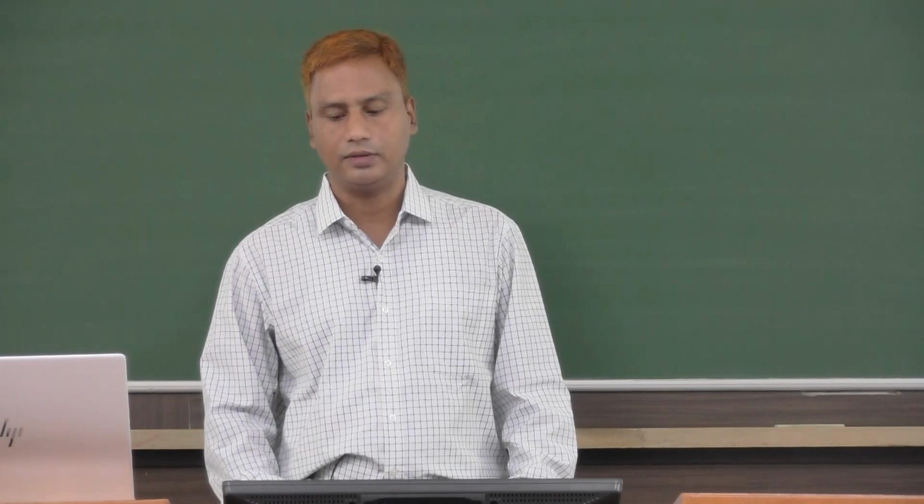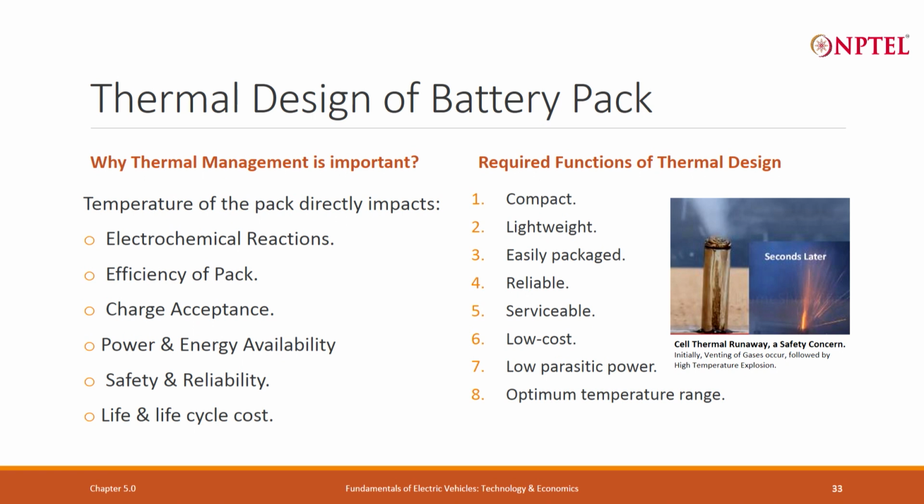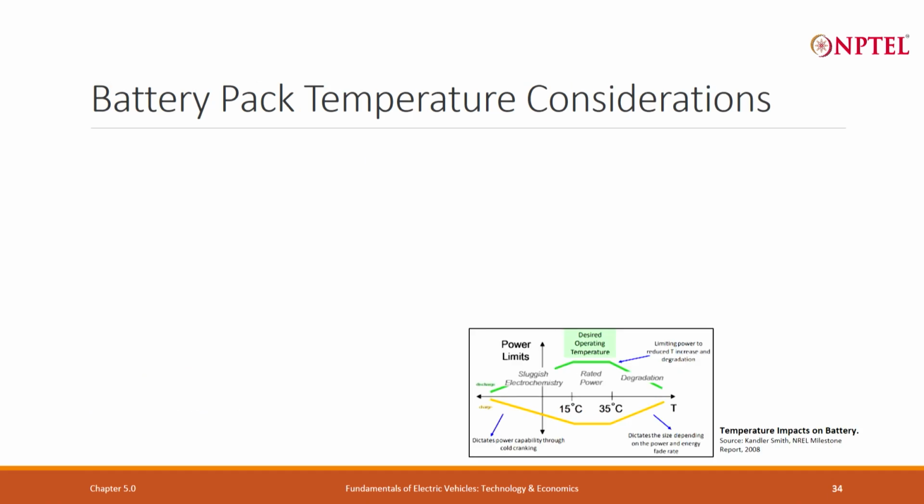What are the required function of thermal design? That also we have gone through: the compactness, lightweightness, easily packageable, reliable, serviceable, low cost, low parasitic losses, and the optimum temperature ranges. That is a required function of a thermal management system or a thermal design. It should also have the small temperature variation among the cell to cell or within the pack. So, temperature gradient, we say that should be very low. And then we have also discussed what should be the optimum temperature range for the operation of the pack.